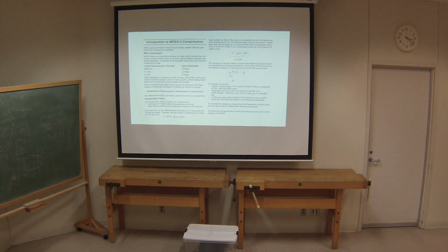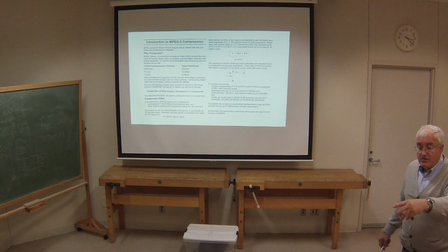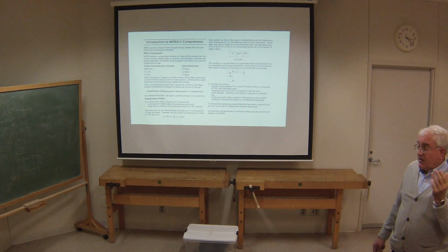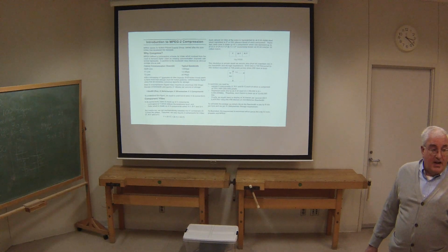Now, how do you formulate a monochrome signal? Well, your monochrome signal is made up of approximately 59% green, 30% red, and 11% blue. So those are your three colors. Now, if you've got any of these color video cameras, they're going to have three color signal outputs.